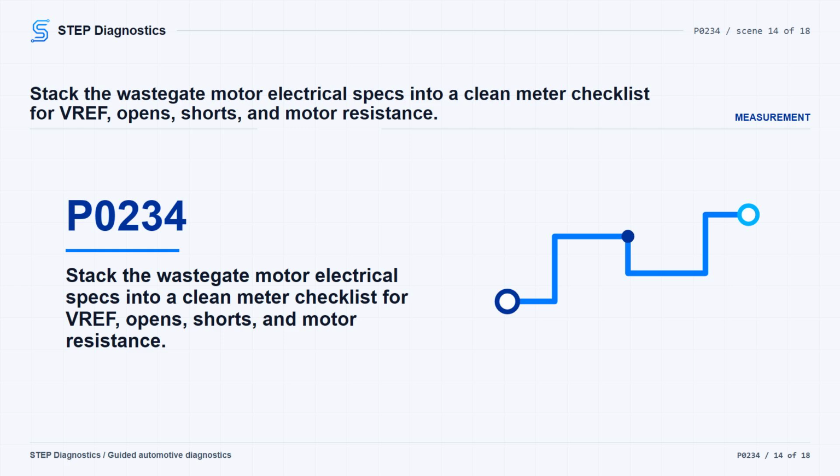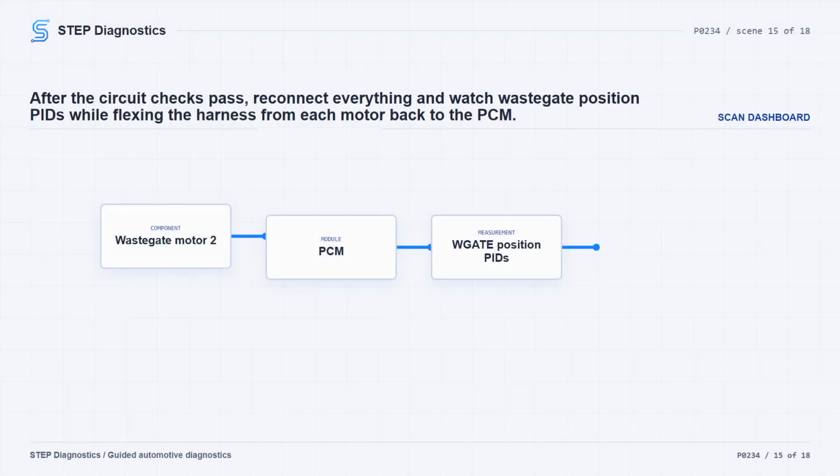If no voltage is present, check the internal resistance of the turbocharger wastegate motor. On the 2.7L EcoBoost P0234 path, measure between C1210 pin 5 and C1210 pin 1 on the component side. It should be between 1 to 90 ohms. If it is not, install a new turbocharger wastegate motor in question and reset KAM.